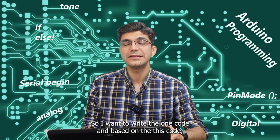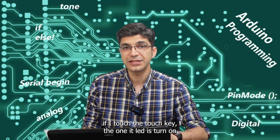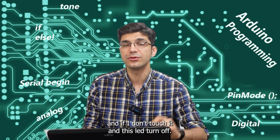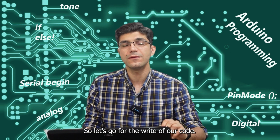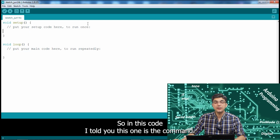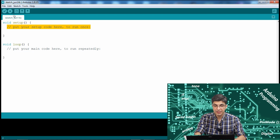So I want to write one code, and based on this code, if I touch the touch key, one LED turns on, and if I don't touch it, this LED turns off. So let's go write our code. In this code, I told you this one is a comment. It means it's for the compiler. Arduino IDE doesn't consider this one actually.